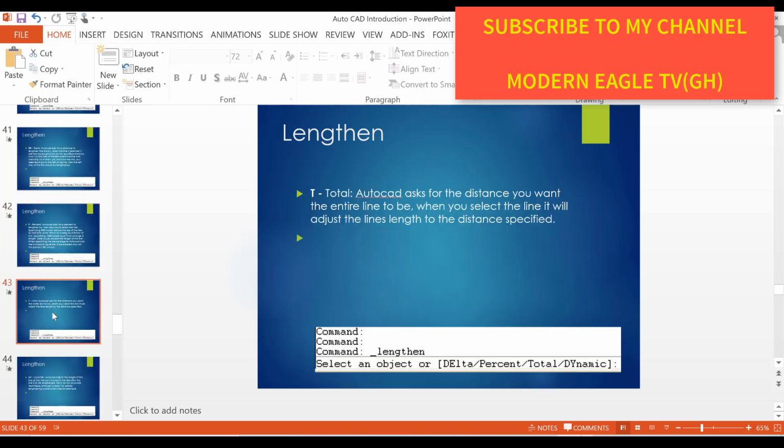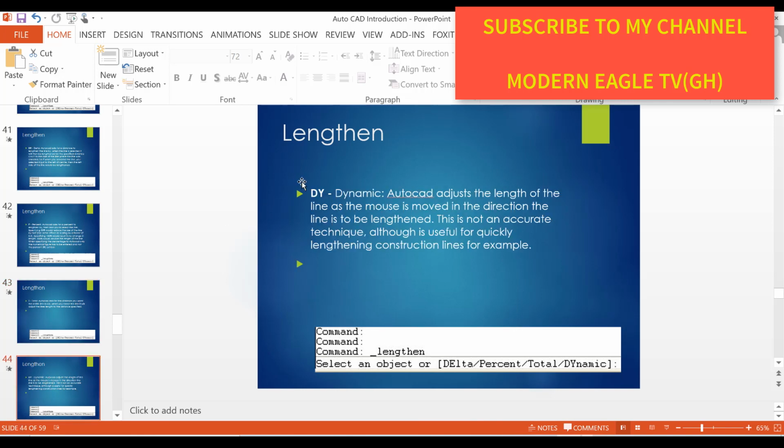T, total. AutoCAD asks for the distance you want the entire length to be. When you select the line, it will adjust the line length to the distance specified. DY, dynamics. AutoCAD adjusts the length of the line as the mouse is moved in the direction the line is to be lengthened. This is not an accurate technique, although it's useful for quickly lengthening construction lines, for example.